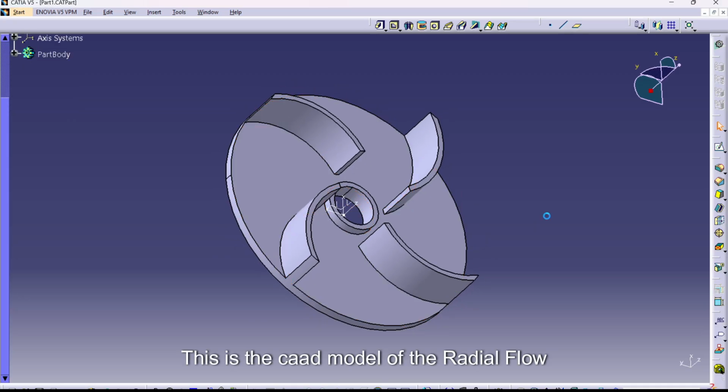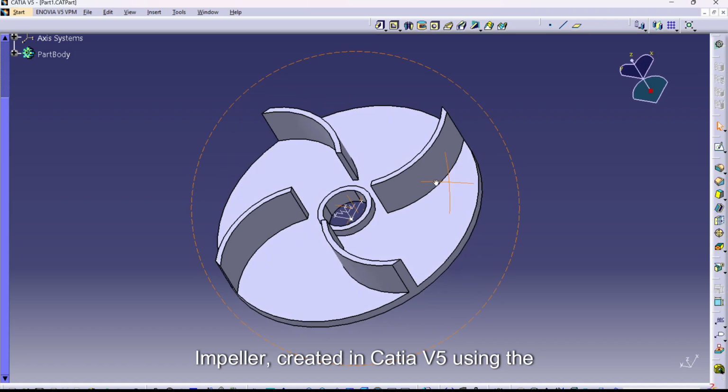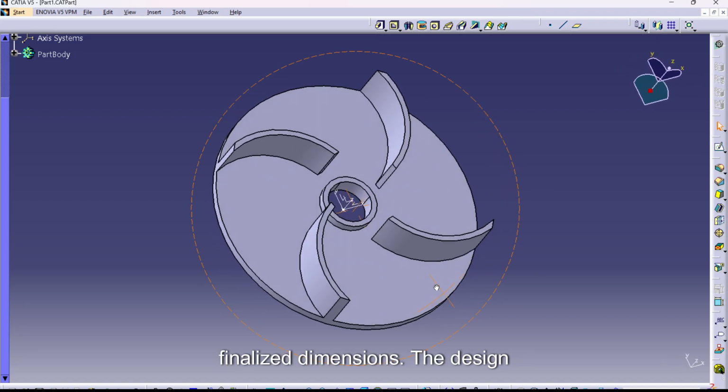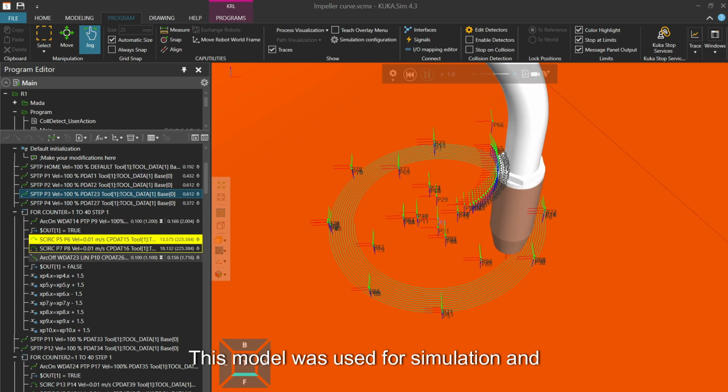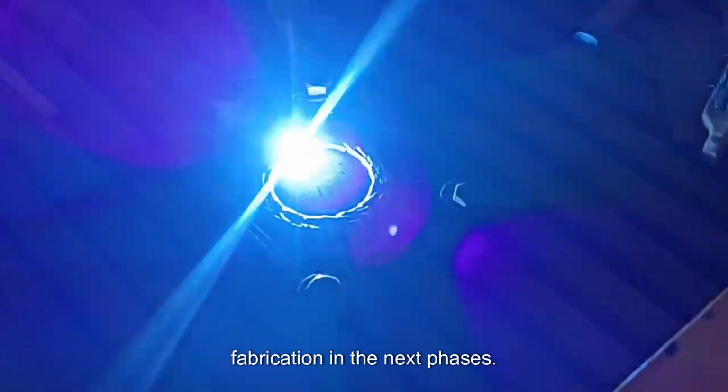This is the CAD model of the radial flow impeller, created in CATIA V5 using the finalized dimensions. The design includes a 144 mm base diameter, 25 mm shaft, 41 mm inner and 44 mm outer blade diameters, 9 mm base thickness, and 25 mm blade height. This model was used for simulation and fabrication in the next phases.